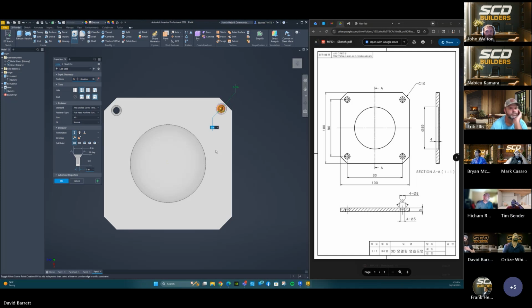Okay. So I'm going to go back a step here just to help you do this a lot quicker. But I'm just going to tell you it real quick. You know how we just made our sketch of this hole. When you're doing that sketch, go ahead and make your other hole sketches too. Don't do one at a time. Because now you already have your dimensions set from this hole. So all you got to do is click that, do a hole, and then go to this one, that one, and that one. It's going to do a hole in each one.